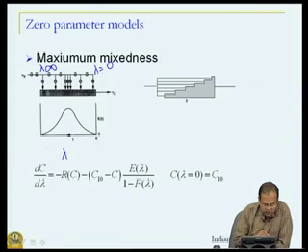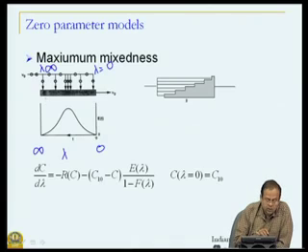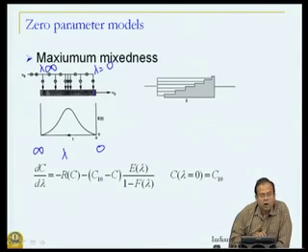So, if I look at lambda, this is 0, this is infinity. What is this equivalent to? The fluid element enters the reactor pretty late, mixes with whatever is there in the radial direction, not in the axial direction. So, complete mixing, and then it leaves the reactor.